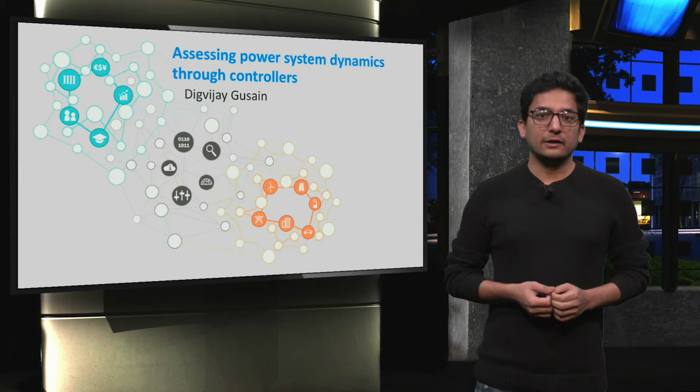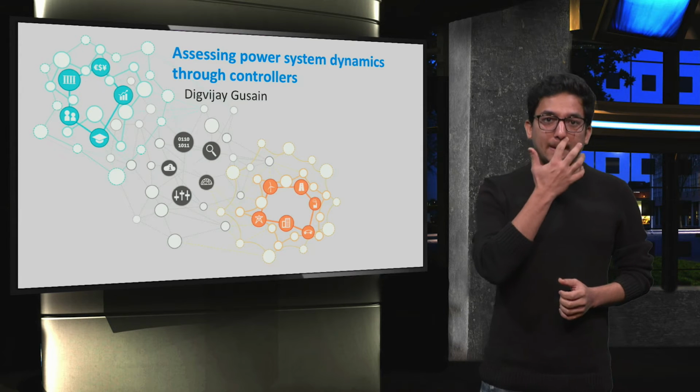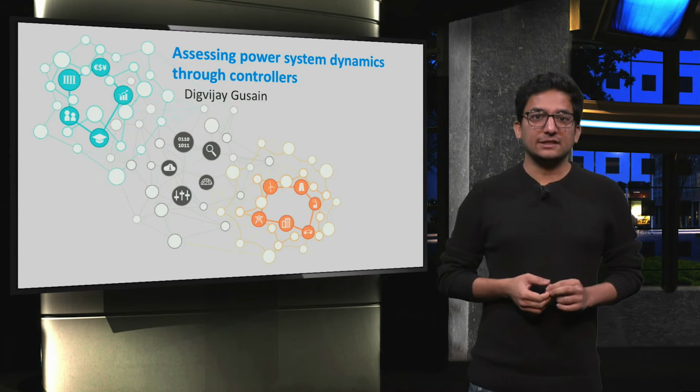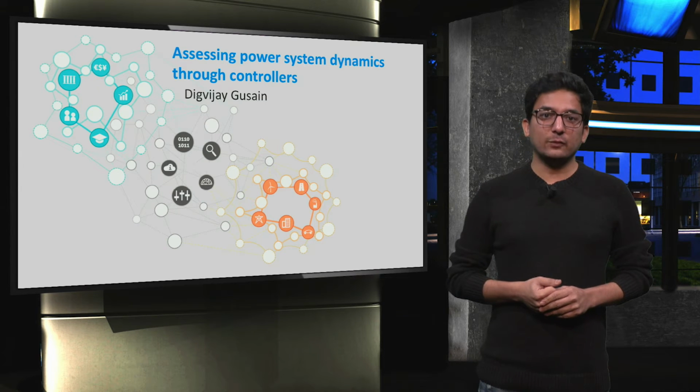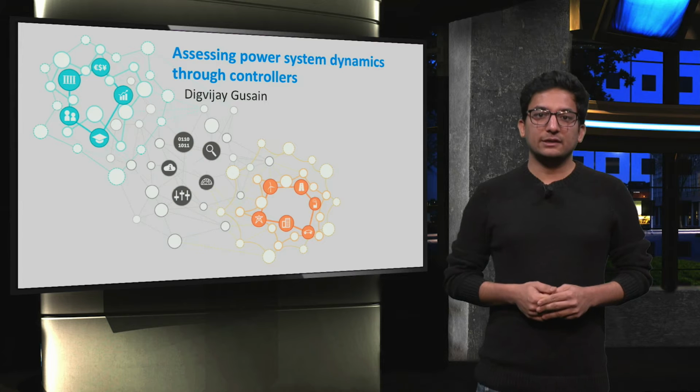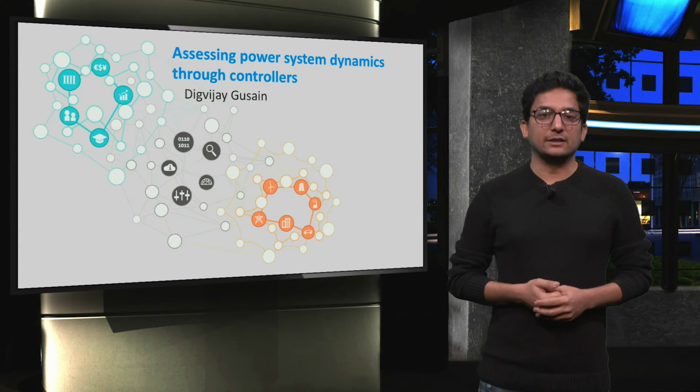An AVR is a feedback control system that measures the output voltage of the generator, compares that output to a set point, and generates an error signal that is used to adjust the excitation of the generator. As the excitation current in the field winding of the generator increases, its terminal voltage will increase. To introduce the AVR, we will need to make some additions to our existing generator model. Let us start with that.